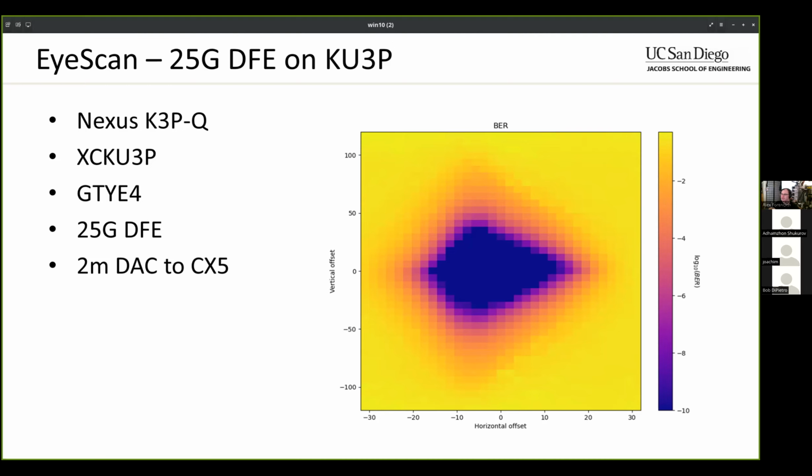But one thing I found with switches is that they usually don't do a lot of auto negotiation. You usually need to force them into the right state. So if you're running an FPGA connected to a switch at 25 gig through a 100 gig port, you'll have to force it into 25 gig mode or force it into 4x25 mode, because by default it runs at 100 gig.